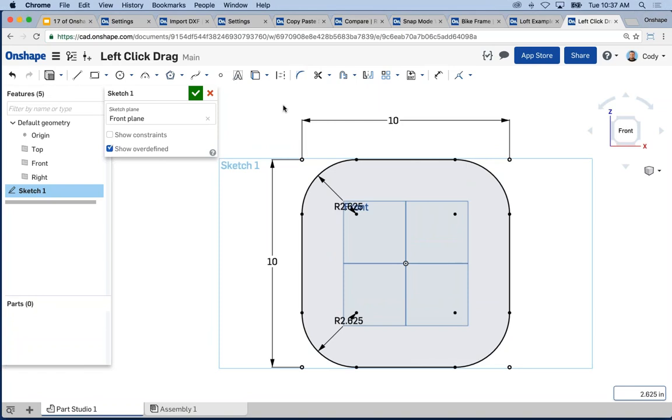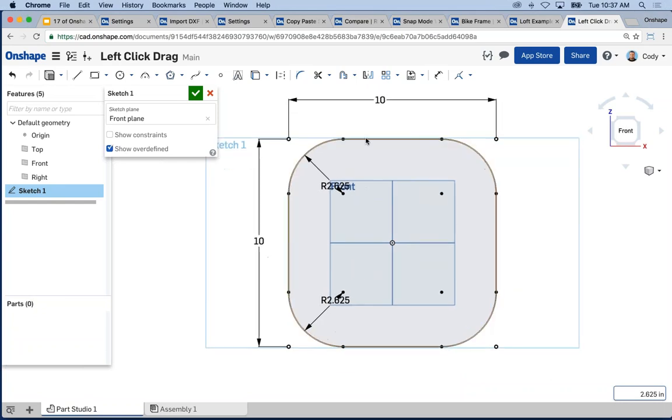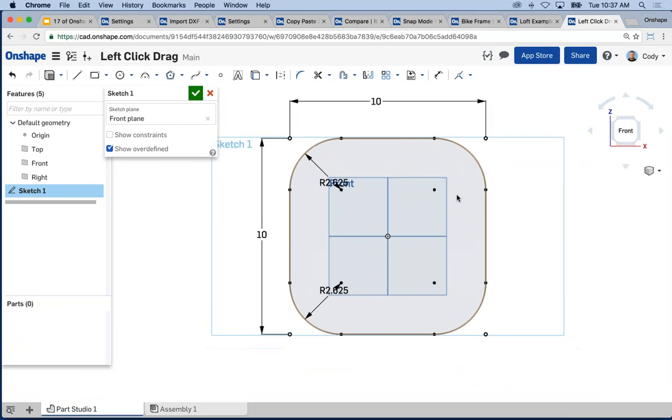Now, the other example I have, and I think it's the more common one, is the offset command. So let's say that I want to offset all of this geometry at once. I could select offset and then select the pieces. And if you've done this, you can left click individual pieces, and it's kind of a time consuming, tedious process. And if you have dozens of lines and arcs, it's not very practical. I can window select. That's another way to accomplish it.